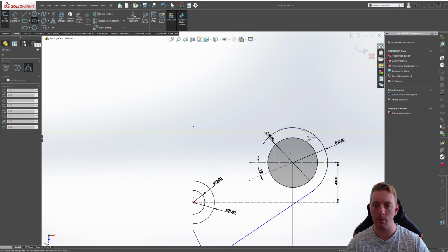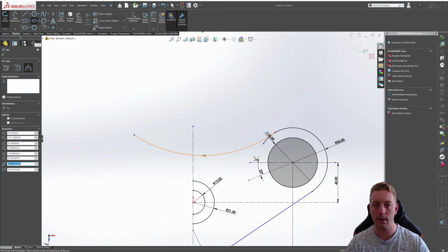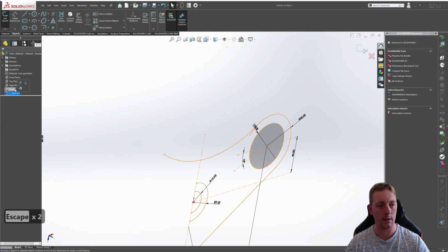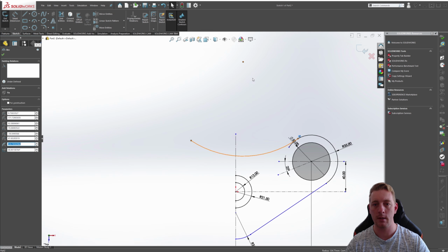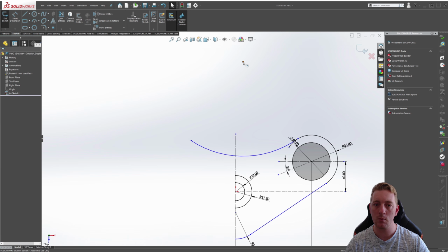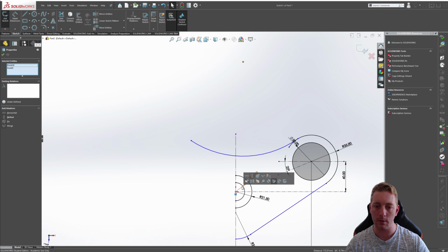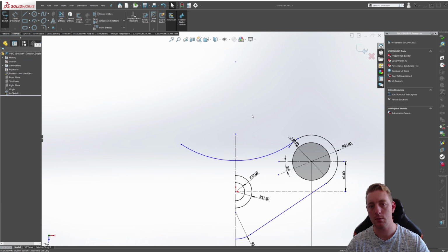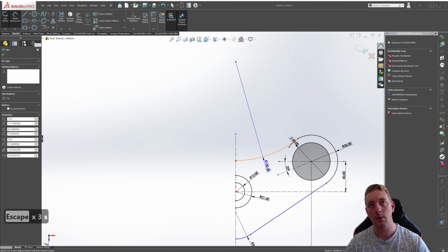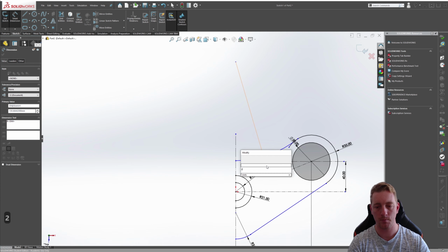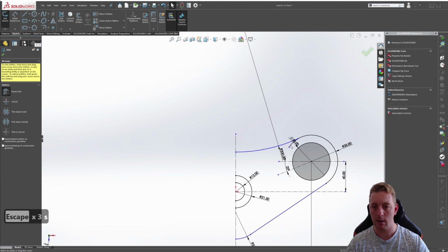Okay, we can do it this way. So we click on this line. We're just going to bring it a bit over and then drop it down. We need to rotate it out so we can go back to normal too. We need the center point of this arc to be in line with that. So we find that point. We can click on this. Let's try that again. We'll use the center point in this case. Okay, there we go. Make vertical. We can trim this back. And our radius for this is 200. And again, just trim this little edge here.